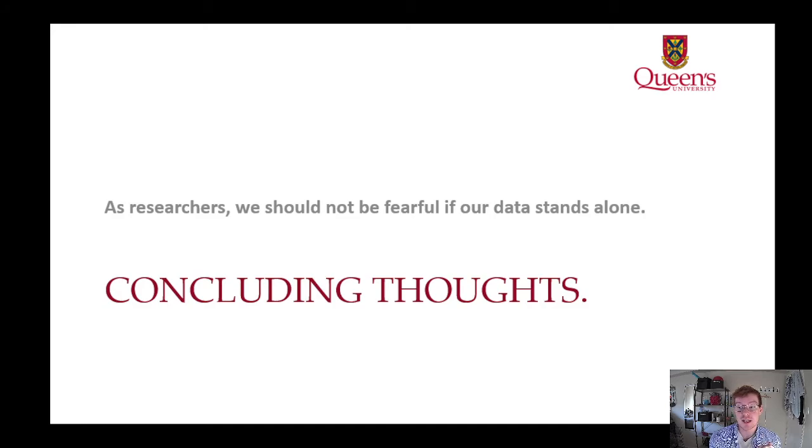Talesnick talks about this negative feedback loop, and I think that to be an apt description, where flawed results are used to reinforce flawed conclusions and present further flawed results to make more flawed conclusions that match the previously flawed conclusion. Anyway, it'll give you a headache if you think about it. But there's been so much interesting research done in soil mechanics which can't really be taken at face value for these reasons. It can't really be taken at face value because it hasn't considered sensor deflection or sidewall friction.